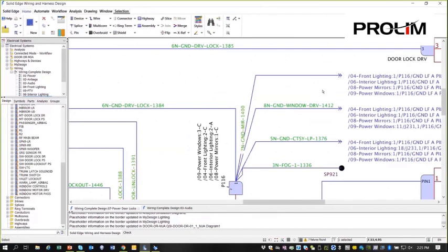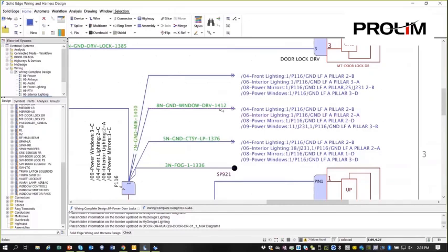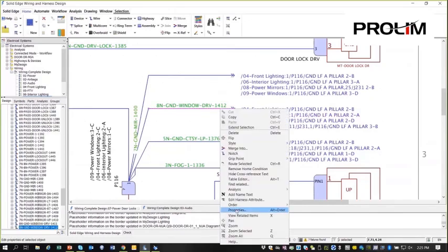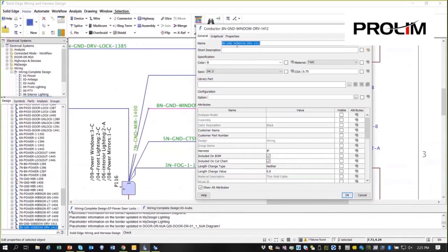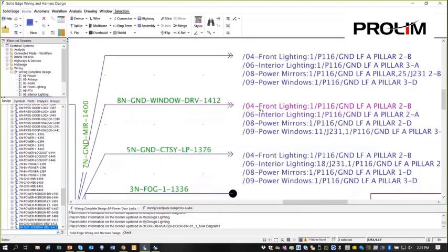I mentioned cross references, for example, in styling. What we're showing here is a wire, and I can look at the properties of that particular wire. The name of it here, it's got a color, and eventually we would add a library part to it in this field here. But what I want to point out is notice that this wire has some off-sheet references. So I know where else I can find this particular wire. It gives the sheet number, the sheet name, and then at the very end, it shows us what quadrant we can find that in the drawing.